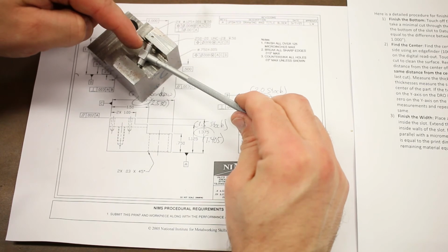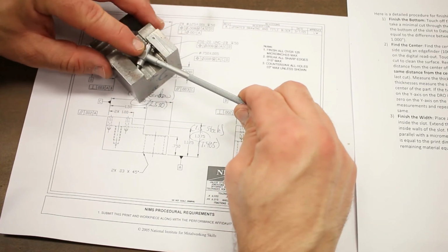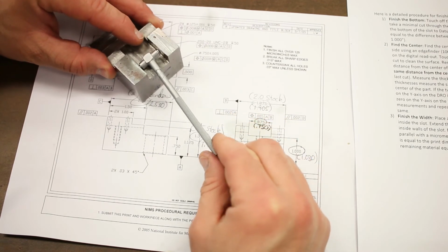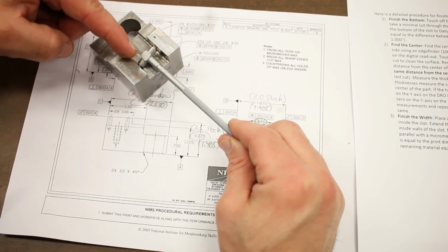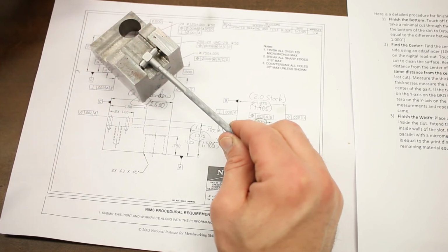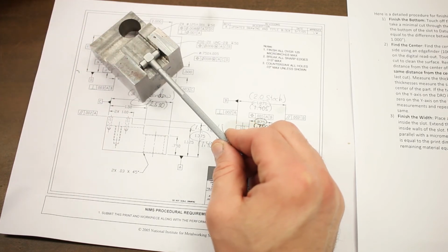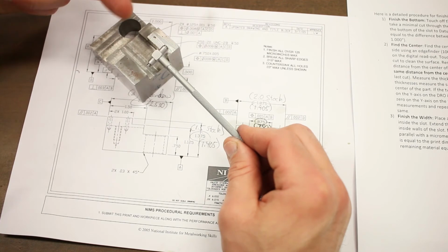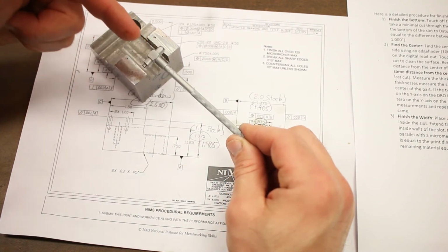But this phenomenon does not occur when you're measuring across two planar surfaces. Like if I open up the telescoping gauge in this orientation and then I rock it through the planar surface, I can be cocked out at a pretty aggressive angle, and it's not going to naturally conform to being square to the slot like that. There's really no good way to get it right on the money. But this is getting very, very close to being the right answer.